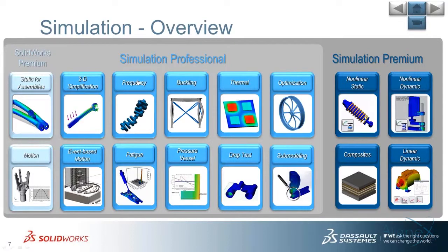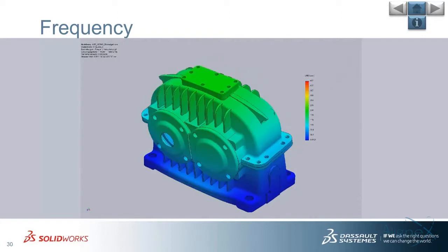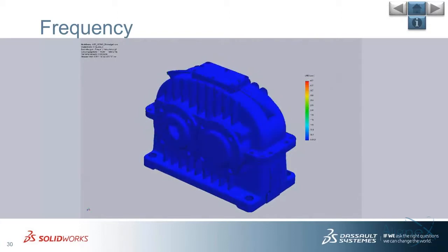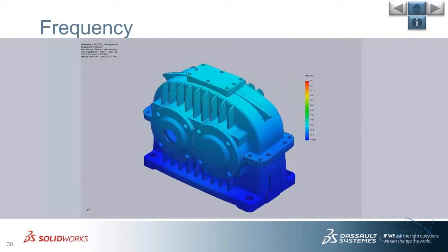So, for example, if you have a structure that's driving over the highway, generally you want to avoid lower frequencies, say between 10 hertz all the way up to maybe 50 hertz. Okay, so frequency analysis allows us to check all the natural frequencies of our structure, and by doing this, we can get our frequency values as well as those mode shapes, how the structure will vibrate if that natural frequency gets excited.